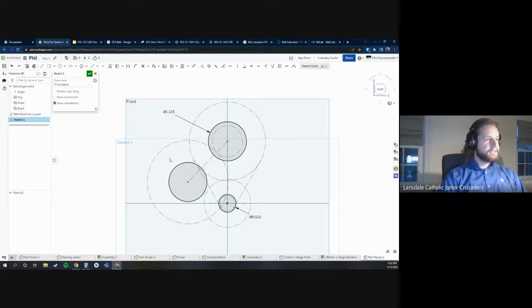And now I just need to make a plate around this. But there's one more thing that I need to consider for the plate, and that's how I'm going to hold the plate together. This hole where it currently is will need to go through a gear, which isn't ideal. And this hole's maybe okay, but I don't have any other places over here where I have holes. So I'm going to draw this circle over here with construction geometry, and I'm going to make a tangent to both of these circles.